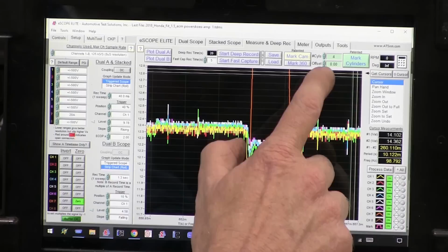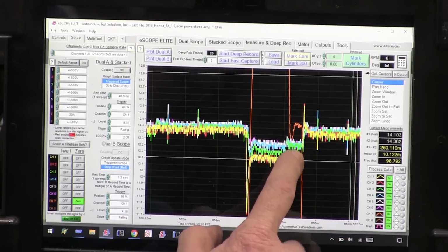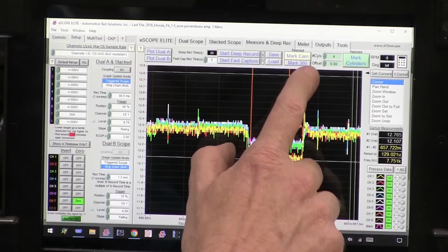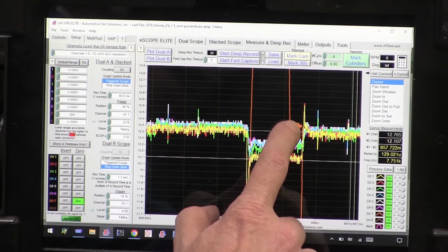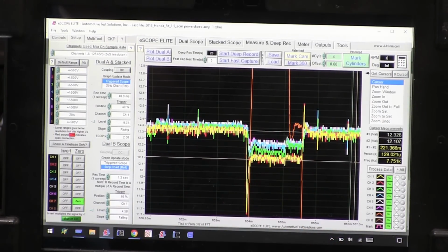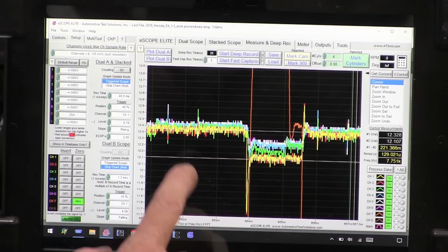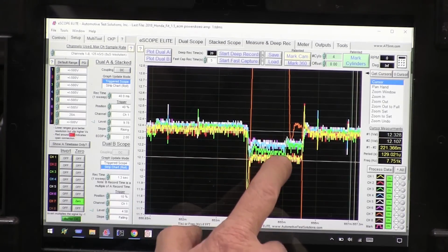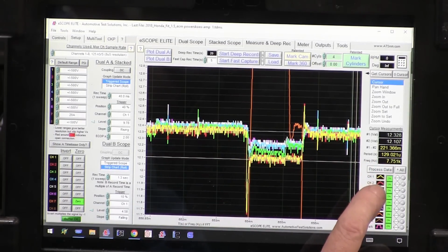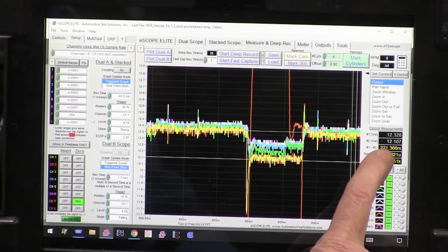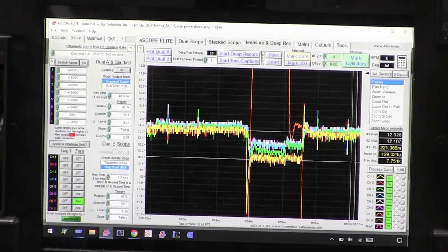And I want to show you something. If we measure our drop, on all the powers you're allowed a half volt. And I'm not going to start chasing stuff till I get more than a half volt. So this is my drop during the pulse. And basically I've only got 221 millivolts of drop.